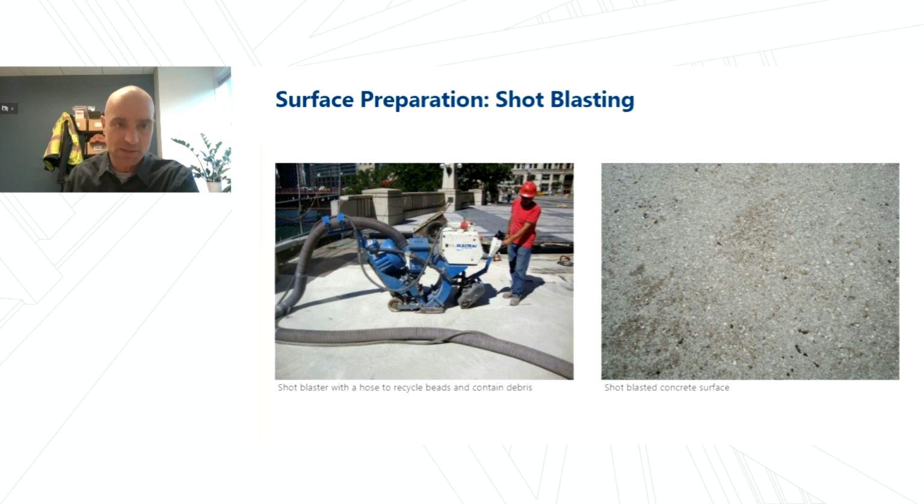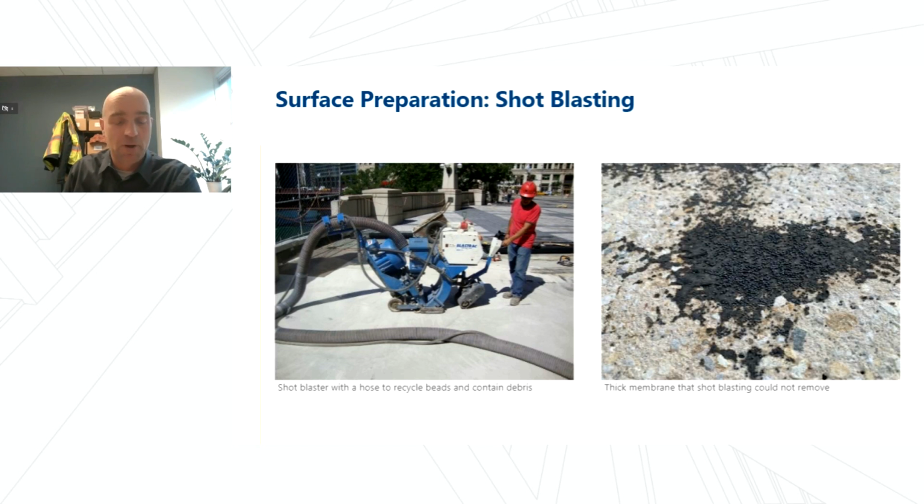This shot blaster is going to recycle the metal beads and it'll vacuum up the dust. We think it's best practice to shot blast both new and repair concrete before adhering a membrane to it. One thing to keep in mind, a shot blaster will not remove thickened sections of membrane. You can see in the photo on the right, the beads will just stick to the membrane.